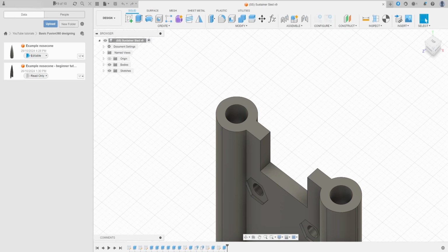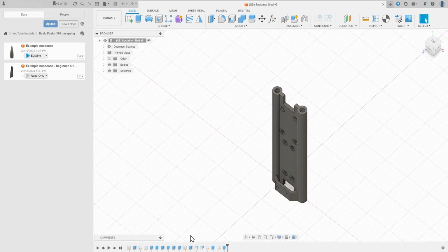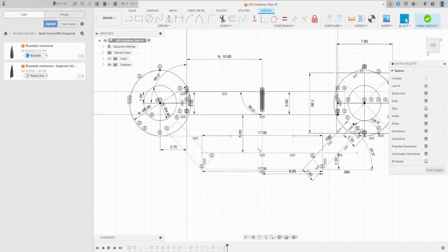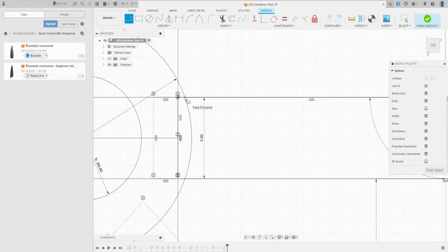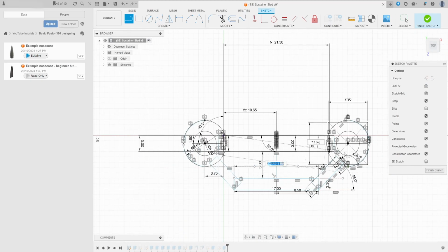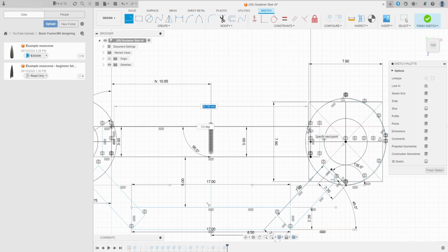If the measurement tool isn't working for what you want, another thing that you can do is you can manually measure it by going into a sketch. I'll zoom out and find a sketch. Now, in here what we can do is we can select the line tool. From here we can measure a specific point that we want. I'm going to select it right there, and then right there. I don't click, but I can see that it's 20.720. That is how you manually measure points.